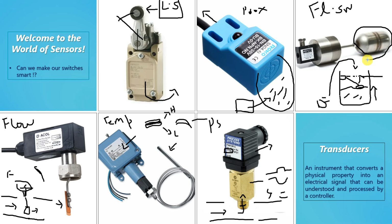Now all of these have some sort of sensing element to them, right? A sensor is an instrument or a device that senses the change in physical properties of a fluid or a process variable that you are monitoring. However, a transducer, in addition to the sensing element, has a transduction element, right? What it does is convert that physical property into an electrical signal that can be understood and processed by the controller according to our requirement.